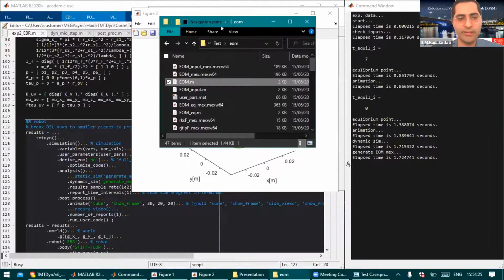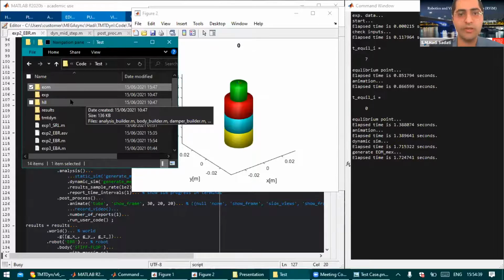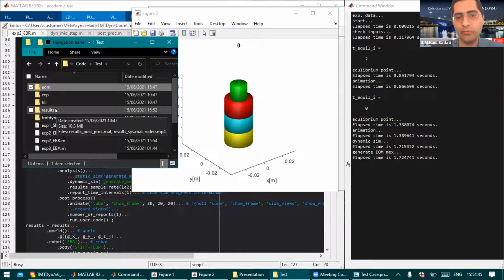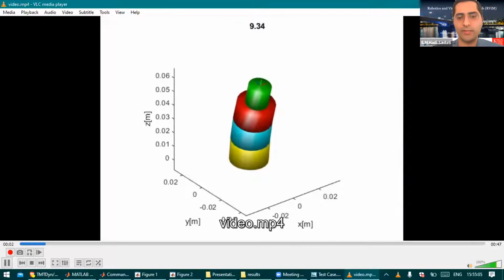But why it does that, and we set a very large value for the input pressure, so I may end up with a stepping issue in the numerical simulation, okay? So be ready for slow simulations if you set irrational values. But just from the previous calculations, have a look here. In the result now we have 2 .mat files. It saves everything in the workspace for you. So just grab it and drop it in the terminal, and you see all of the plots that were generated before.